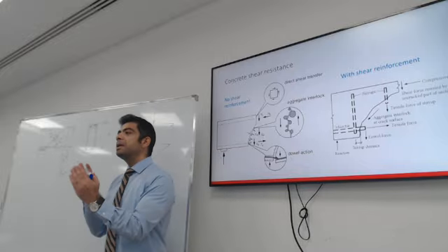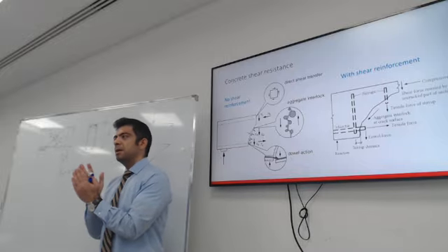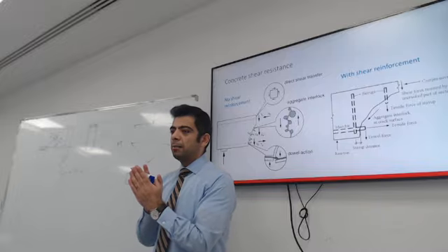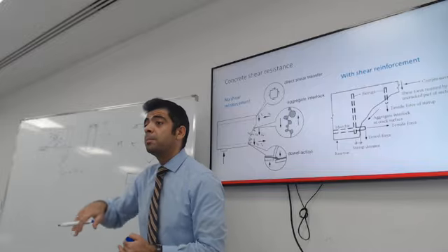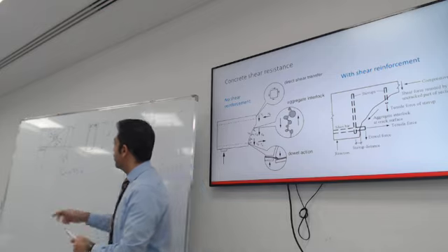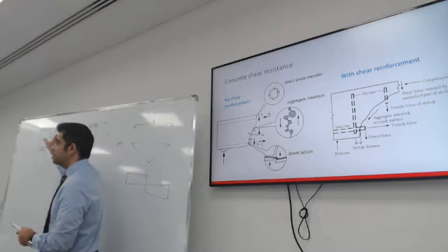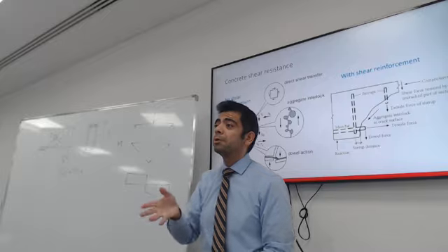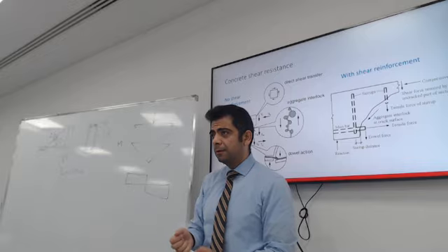So there is also a minimum spacing. Minimum spacing will allow concrete to flow in between the stirrups. Think, if you have a lot of stirrups, concrete will have a difficult time flowing in between the stirrups. Do you have a question?